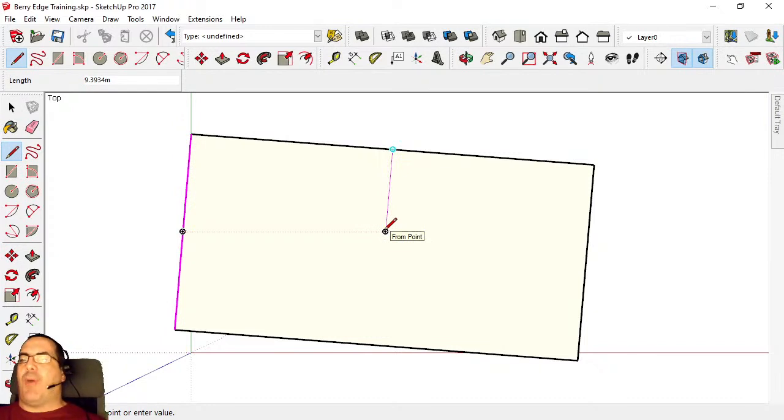And this is an important thing to remember, because when you're doing this kind of modelling, your lines have to be perpendicular and they have to be straight. If they're not, you will get all sorts of odd bits of geometry all over the place, and trying to change some of them and sitting there spending hours deleting tiny little triangles and zooming right in can be a bit soul destroying, believe me. So try and get them as accurately as possible.